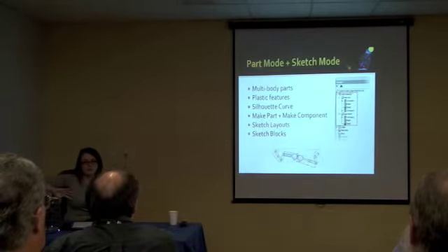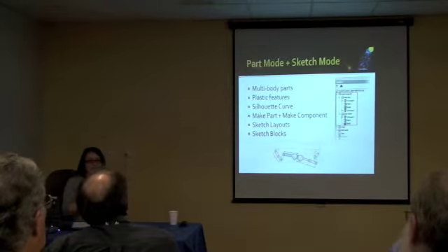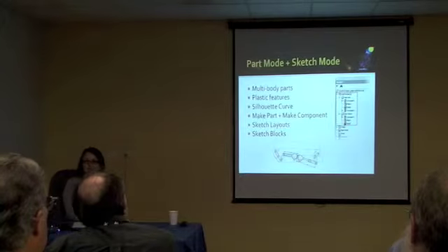There's an option to make part and make component, which will allow you to take your skeleton model, which you've used the new multi-body part option on, and just automatically create your assembly for you. There's a little trick to that. Again, I'll be displaying that later.